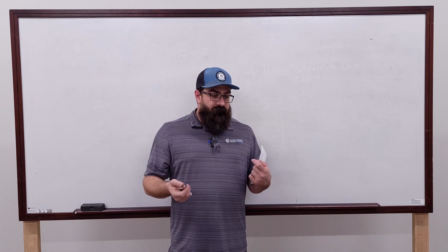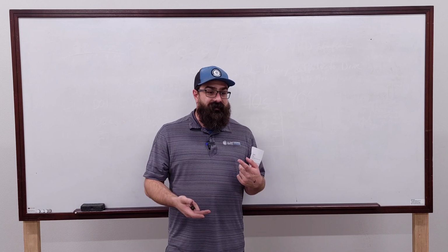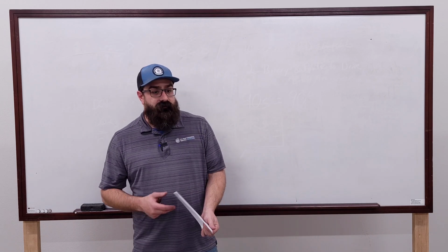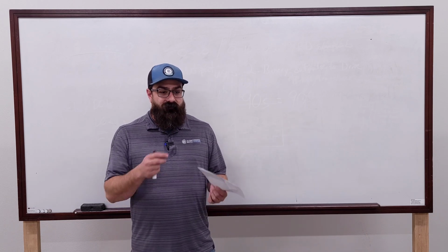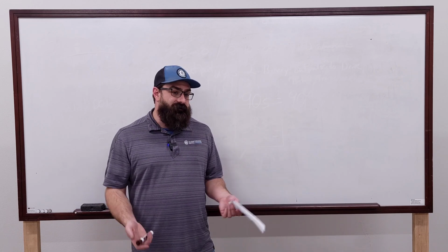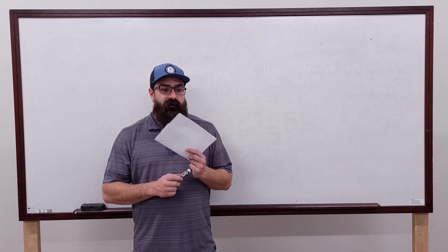So you fire that output, you should see 24 volts, you take it off, you should see something less than 24 volts. It's still going to show some voltage just because it's solid state, right? It's never opening up a set of contacts and closing off. You may see like 3 volts, 5 volts, something around there. But as long as it's not at 24, it should be off.